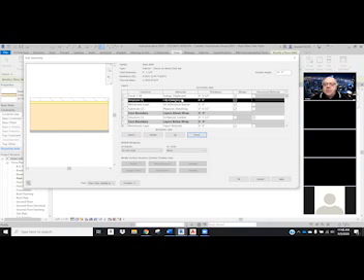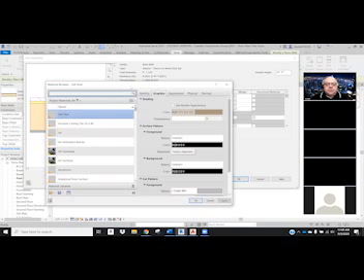And this substrate, we're going to change its category. By category, I mean we have to define that. If we leave it blank, the program, Revit, will treat that as an error, and it won't show up in any of our renderings. So we want to click on that, and then we get three little dots. Those are called ellipsis dots, if you remember from your English classes. We click on those, it means more to come. And it's going to bring up another dialog window.